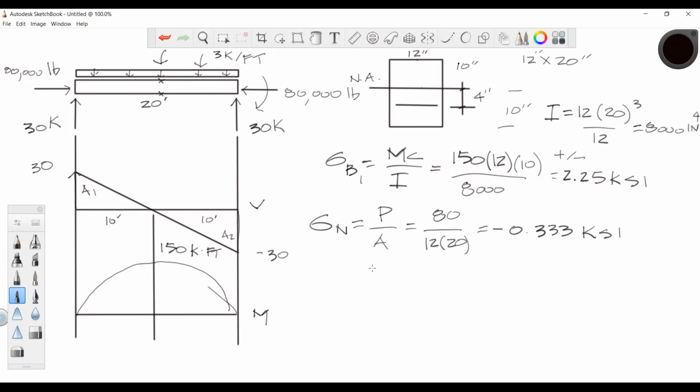So we have one more bending stress to develop. The bending stress due to the fact that these cables are below the neutral axis, so they're compressing the bottom fiber and tensioning the top. And we're using this equation now, MC over I, where M is the force times the eccentricity, so P times e times C divided by I. What is the force here?